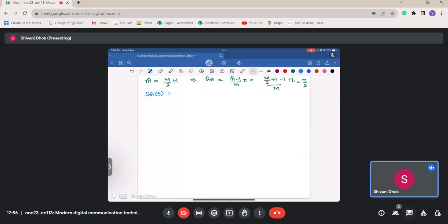So let's go with the simplest case where m hat is M/2 plus 1 and θ_m hat comes out to be π/2. For this case, s_m hat(t) has only g(t) sin 2πf_ct. Now let us apply the Gram-Schmidt step.